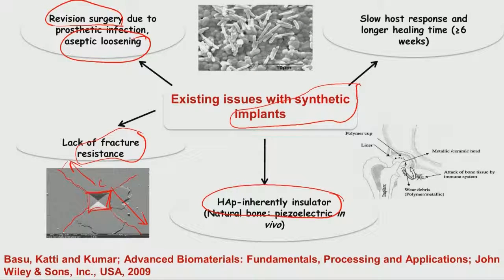Smaller is the crack length, like one material has this much crack length and another material has such a large crack length. So, certainly the material which has such a large crack length is not able to resist the crack propagation when indented at the identical load, compared to the material which shows very small crack length. So, this kind of qualitative comparison tells you that